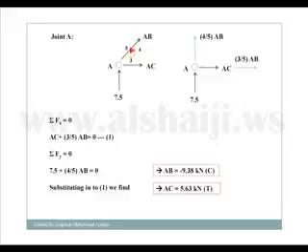If my assumption is correct and my number is positive, let's say we have AB, and I did the calculations and got a positive value for AB, that means my assumption is correct, and the force is in tension in AB. And if I get a negative value, that means the force is in compression. So draw the joint, draw the members, and draw the arrows pointing away from the joint. Third, we will add the external force to our joint.